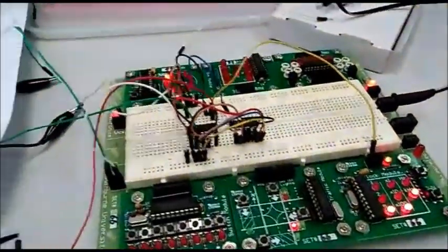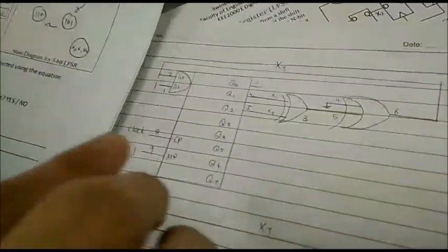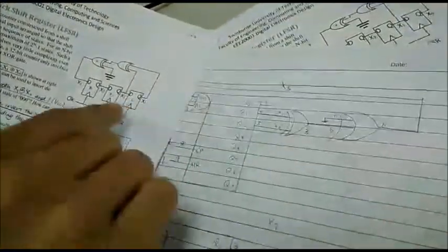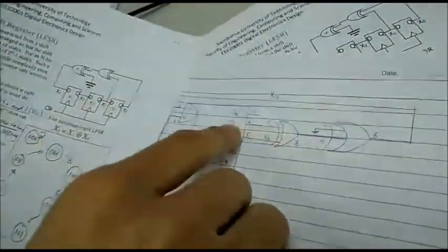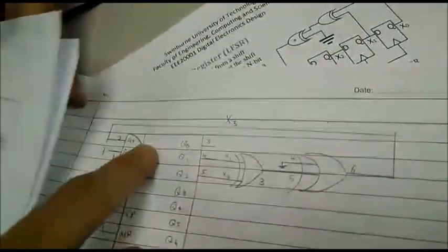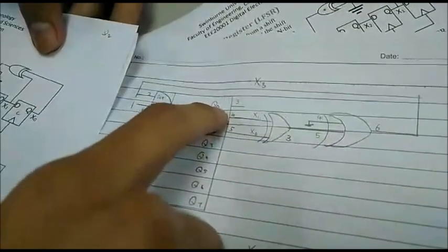So we constructed this circuit using the shift register. You can look here, and this is the schematic. This is the schematic of the 3-bit left linear feedback shift register. The reason we connected X1, in this diagram, to Q1 here is because, as you can see, the input here feeds the input of Q0.